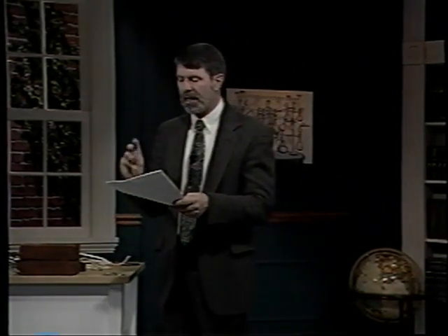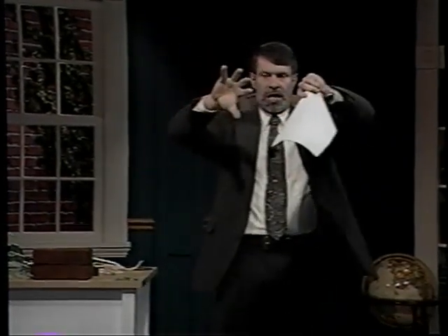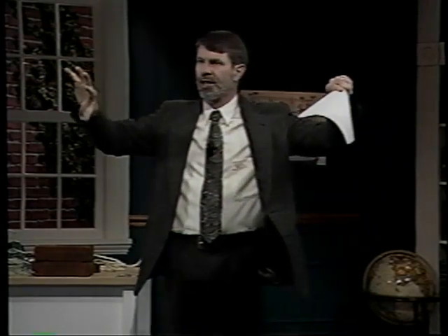Our second physical property is thermal expansion. This is the tendency of materials to change their dimensions when they're heated. Now, thermal expansion is another property that's absolutely dependent on the behavior of the atoms and how they're bonded together. Most materials will expand slightly when they're heated. In these materials, like a bar of metal, for example, you have atoms side by side. And as you heat up the material, each of those atoms starts vibrating more and more vigorously and starts colliding and bumping into its neighbors. And naturally, this applies a force, and that force tends to make the whole material expand slightly. So the metal becomes larger and larger as you heat to higher and higher temperatures. That's the normal behavior, and almost all materials do that.